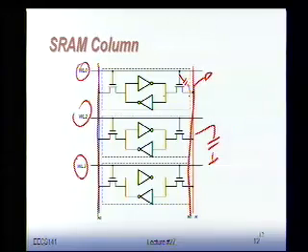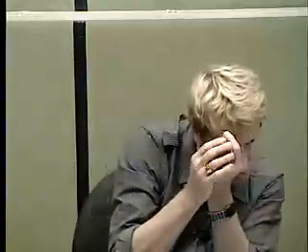Very small. So I'm going to make all those transistors minimum size if I can. The smaller the better, because my cell gets smaller. So I have a giant problem, a huge problem at hand. I have this tiny little transistor that has to move that big capacitance up and down. So what can I do? Any idea? Any idea of how you can do that? A very small transistor move a big capacitor. That's a tough task at hand, right? It's not an easy thing to do.